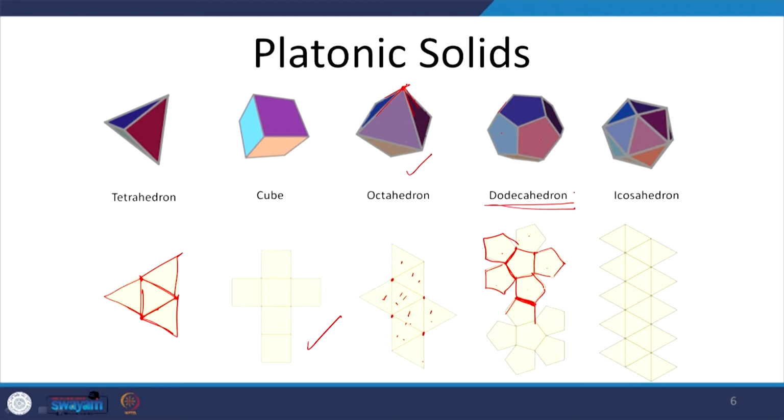If you look at this solid, which is here in my hands, we have developed this dodecahedron using the pentagons. The base surface is a pentagon. So we start drawing this pentagon, and you keep developing the pentagonal surfaces, and once you put them all together, in case you have to develop it, right now it is only what will be seen on this surface. If you have to make space for sticking it together or welding it together, you have to have some little extra pieces, which is what we will draw along. So we know how these surfaces are going to be joined.